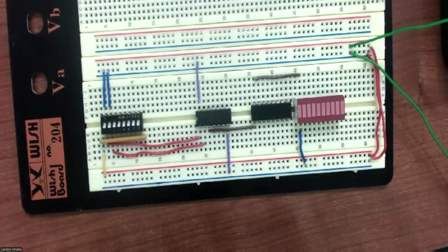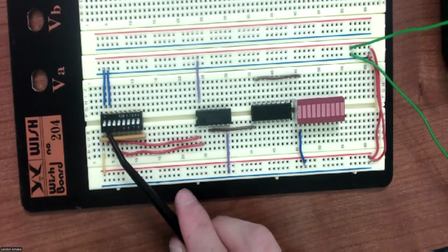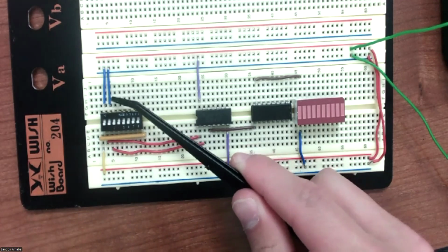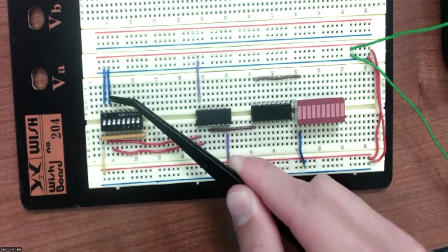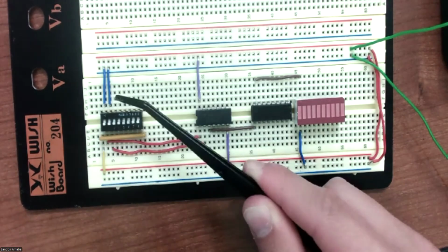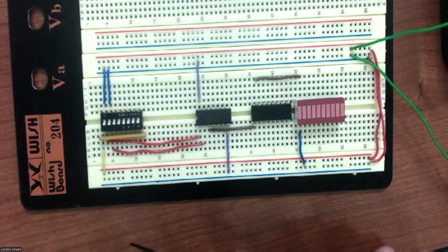Since we're going to be doing a basic NAND circuit today, I've only wired these first 2 switches. You can see on the opposite side, we have both of these switches tied to ground. This is going to be a simple switch layout that you are going to do every single time when you design a switch and LED circuit in this class. It's very important that you learn this layout and you're able to replicate it consistently.